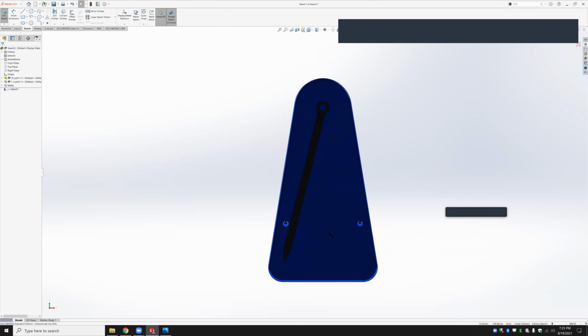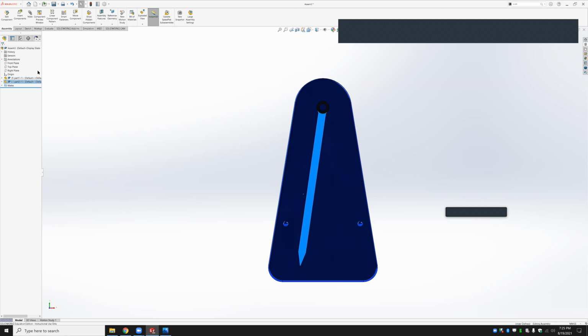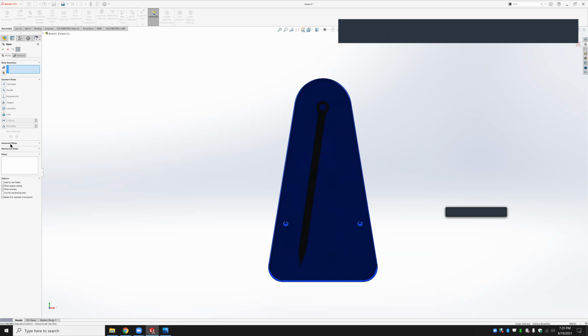So basically the angle from here to here is 30 when you account for the thickness of the needle. I'm going to exit my sketch, and what I'm now going to do is go to mate, and it's an advanced mate. The last one it looks like is called limit angle. The first angle there, you don't need to worry about. That's asking what the default angle is where it's starting off. We don't really care about that.